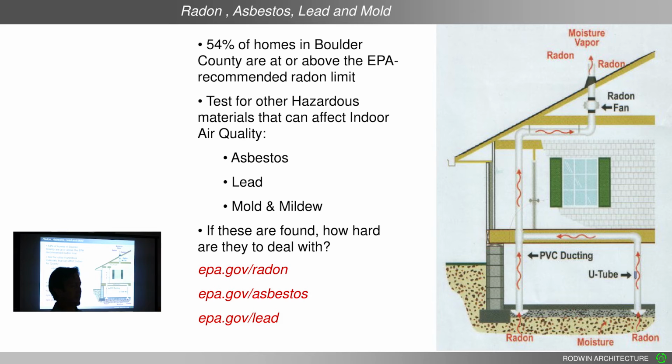It's not dangerous if it's encapsulated. So if you go into a house and you've got something like those checkerboard flooring tiles in a basement built in 1956, that is almost certainly asbestos material. But you don't have to do anything to it, because as long as it's not particleized and airborne, it's not going to get into your system. So you can encapsulate it. You can put paint over it. You can put carpet over it. If it's popcorn ceiling, I'd worry a little more, because it can become friable, airborne very, very easily. So if you are putting a new planter hook into the ceiling, that dust actually is likely to get inhaled. It's extremely carcinogenic. But as long as you're not doing anything to a house, you don't have to remediate it.